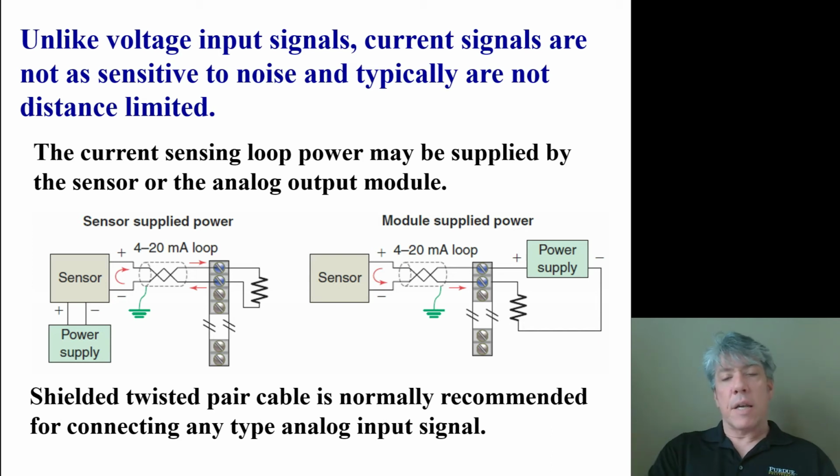The extreme right hand side diagram though, shows just a loop where there's only 2 wires going to the sensor. Turns out there are 3-wire sensors as well, but don't worry about those. 2-wire sensors are usually cheaper than 4-wire sensors. 3-wire sensors are a good trade-off between them. 3-wire sensors can have ground loops, but again, don't worry about 3-wire sensors.